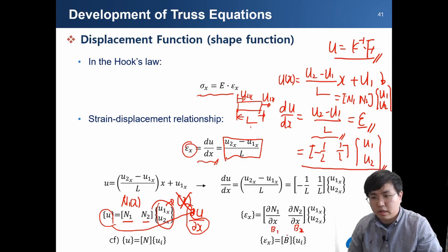To express the strain field, we are going to use the B matrices. The B matrices are the derivative of the shape functions.